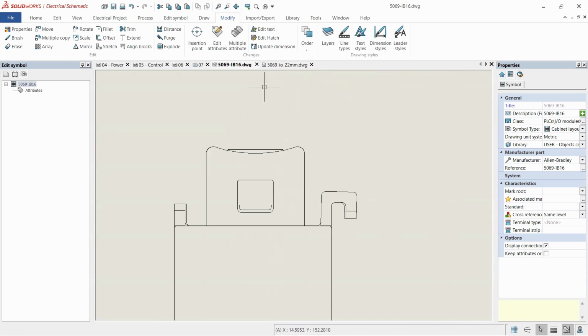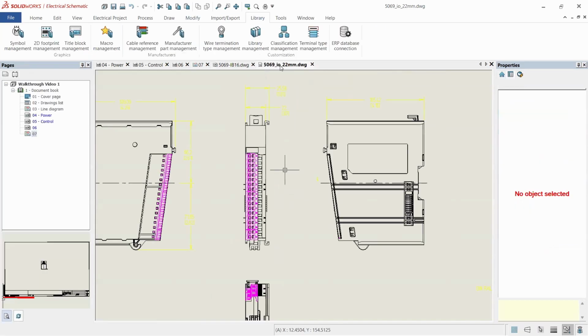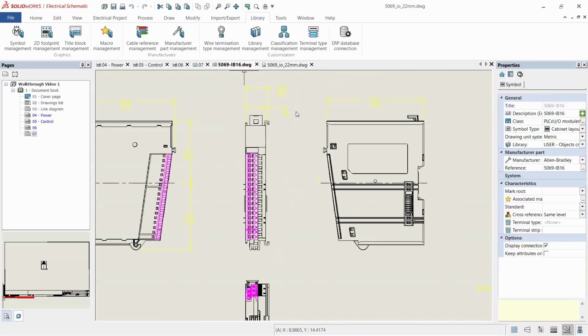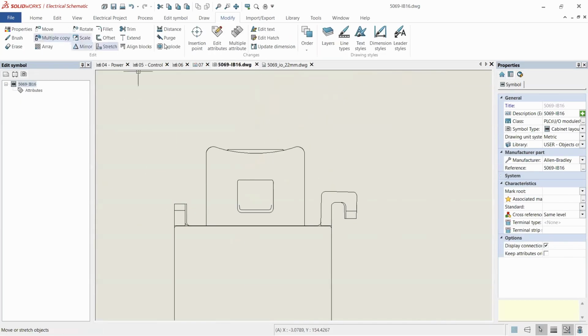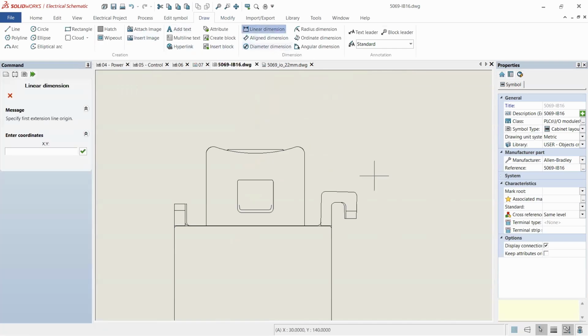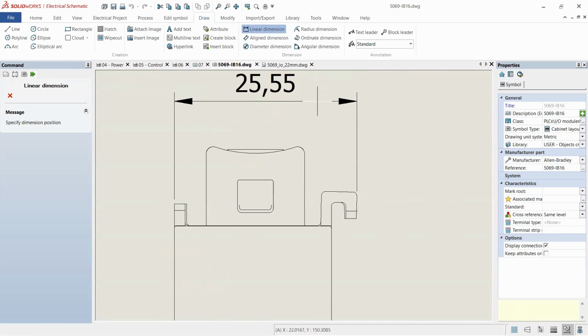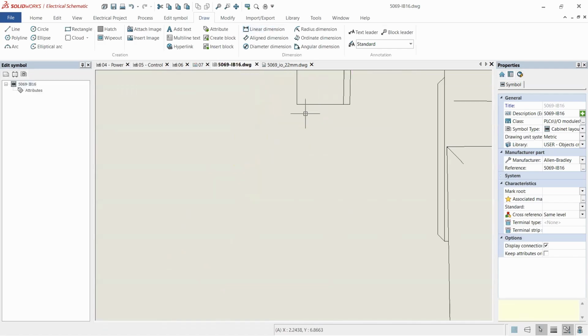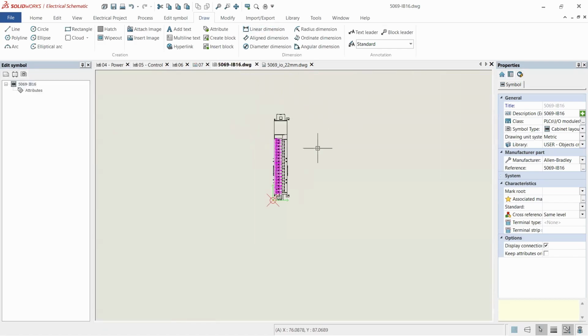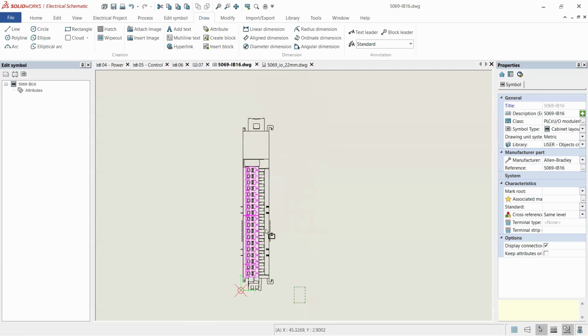That should have been something like 25.56 millimeters, tab to tab. Let's check. We have dimensions. Where are you? Under the draw tab, dimensions. And let's kill my snap because it's stopping me from getting the parts I want, here to here. 25.55. I'm kind of okay with that, right? We're off by 0.01 millimeters.